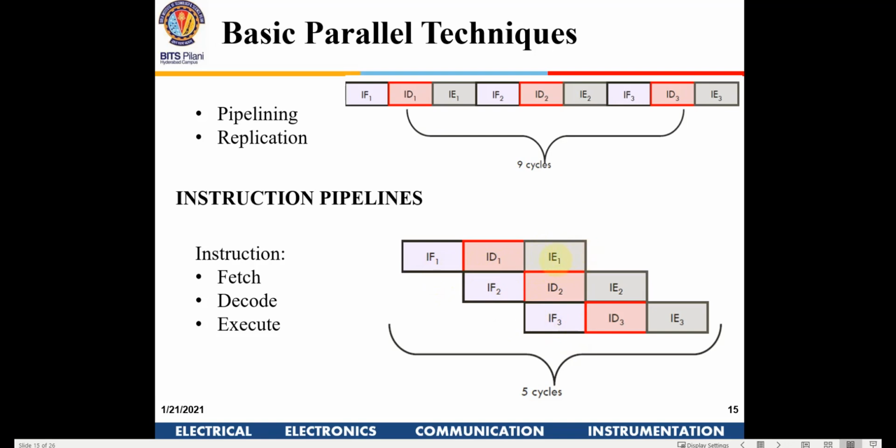The ALU is doing the execution, and the ALU is doing only one execution at any given time. At this instance, the ALU is executing the first instruction. At the fourth cycle, the ALU is handling the second instruction, and in the fifth cycle it is doing the third. There is only one ALU. It is not a multiprocessor. It is the same processor, but you are staggering it. You are doing a kind of parallel processing, keeping the data ready for the ALU. This is known as pipelining.